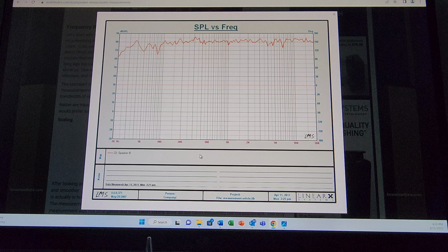And in this case, I'm going to zoom in right over here on the speaker because we haven't changed the positioning of the speakers in the room. We haven't toed them in, we haven't moved them forward, we have not turned up the gain on the amplifier. What we have done is run 5 separate sweeps and got 5 different results. Now the question would be why? I'm going to exclude for a moment the red line and the orange line because in these two instances we used an attenuator to control the speaker, particularly the tweeter. And on the other 3 graphs, the green, purple, and blue, there were no adjustments whatsoever.